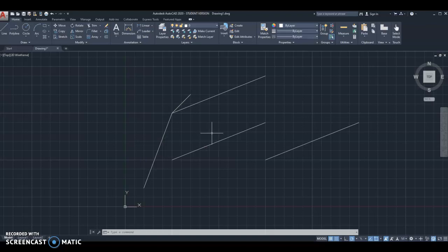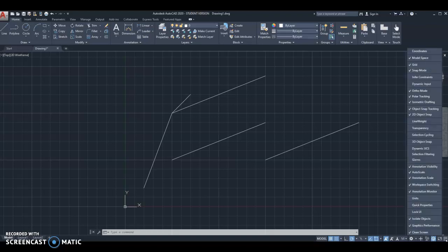So when your dynamic input is turned on, relative coordinates are default, and you have to use the number sign to indicate absolute coordinates. Now, I personally am not a huge fan of the dynamic input, and so let me show you how you can turn it off. Many students do like it, so you don't have to do this, but I'm just pointing this out just in case. If you click the 3 lines down here in the lower right, all of these check marks indicate the options that are appearing in this bottom tray. So right now, dynamic input isn't even an option.